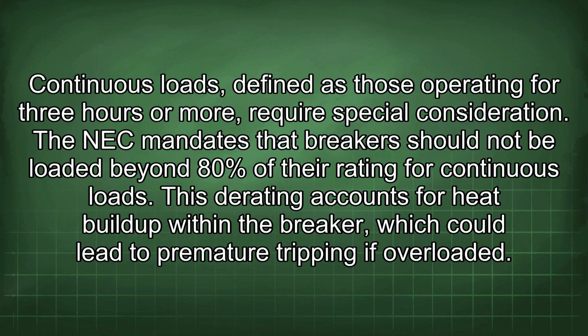Continuous loads, defined as those operating for 3 hours or more, require special consideration. The NEC mandates that breakers should not be loaded beyond 80% of their rating for continuous loads.